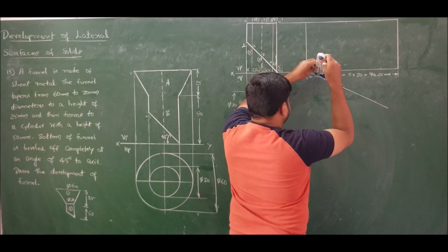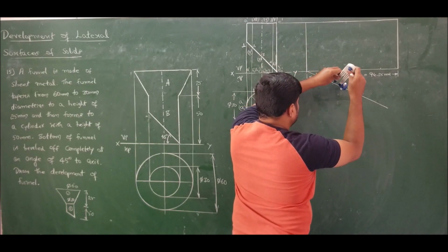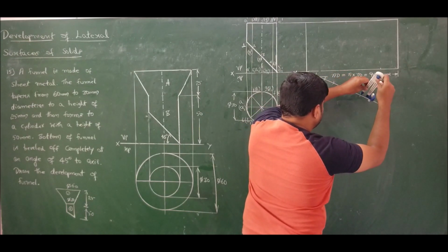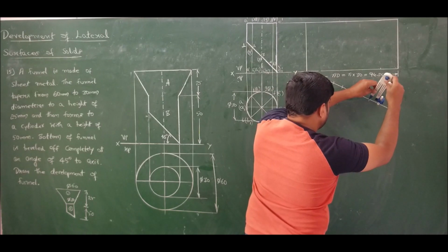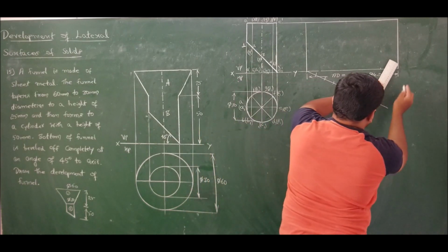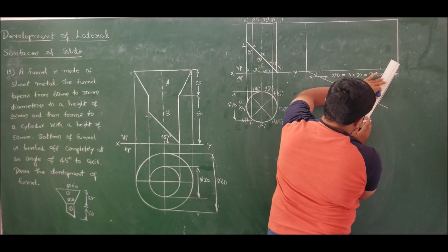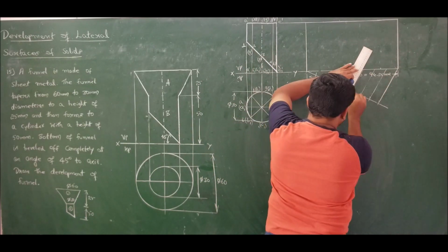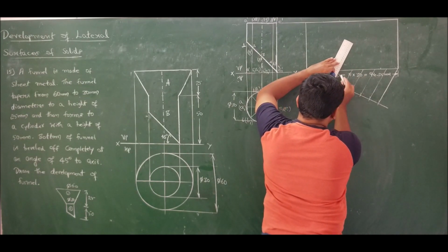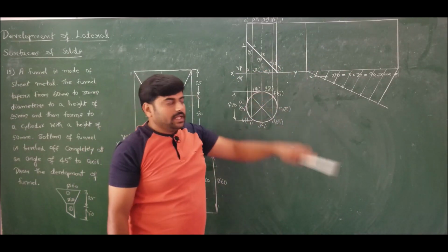1, 2, 3, 4, 5, 6, 7 and 8. Done. Now connect the last one to the last one. Now you draw parallels like this. Keep drawing parallels, and you will get 8 equal divisions. Yes, we have divided 94.25 into 8 equal halves.